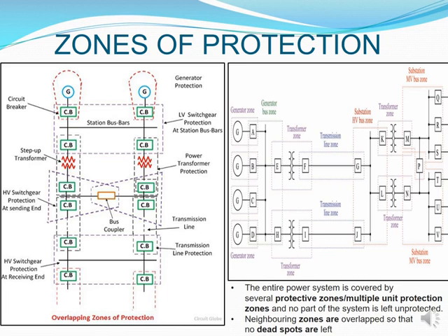You have a line, and then you've got other circuit breakers and a bus bar and another set of circuit breakers. So what you really have here is a generation that is going through to your transmission network, and then it will go through up until where you have your last transmission substation. Hopefully at that point it will be going out to where your distribution is going to be. Now, when we talk about zones of protection, we're talking about this type of system.